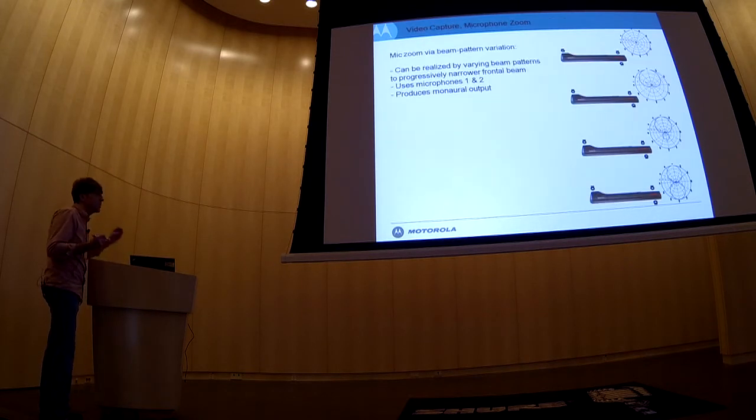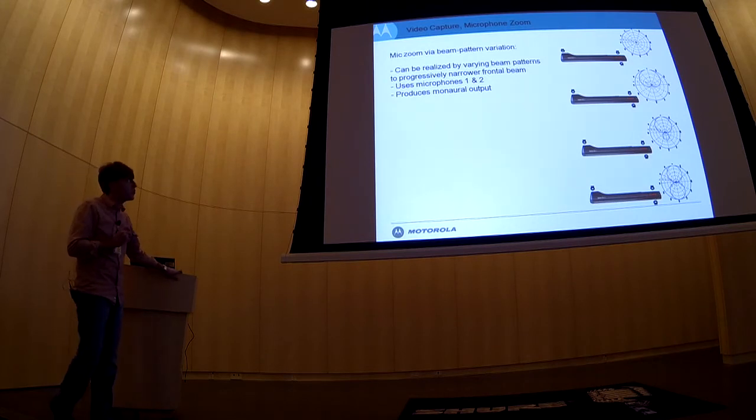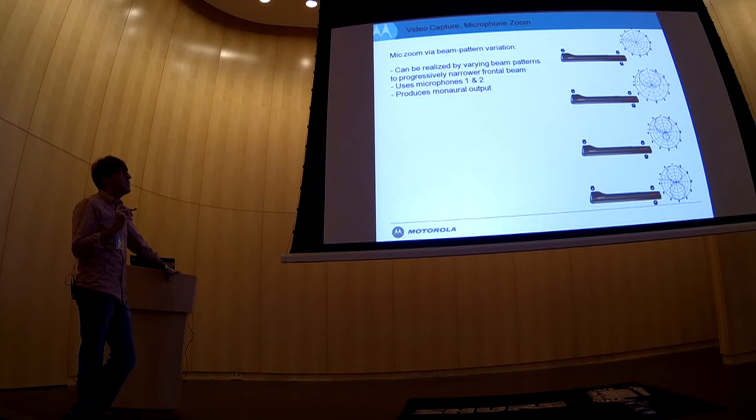All kinds of possibilities. Here we try to illustrate the microphone zoom by beam pattern variation. If we were to start with the bottom microphone pair and form a cardioid oriented towards the subject of the video, we already know that that pattern can vary.